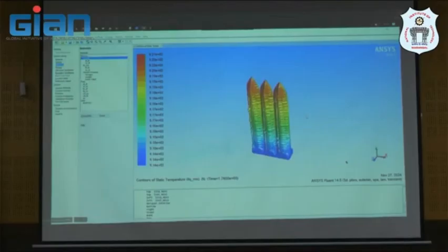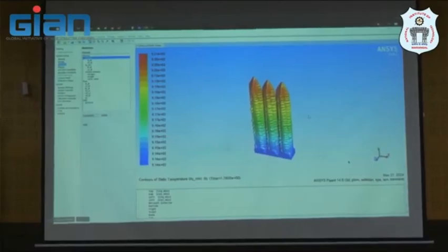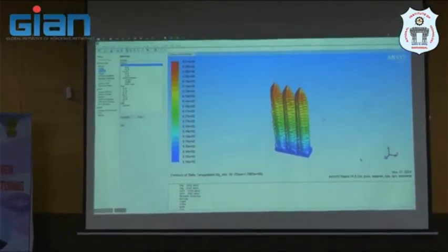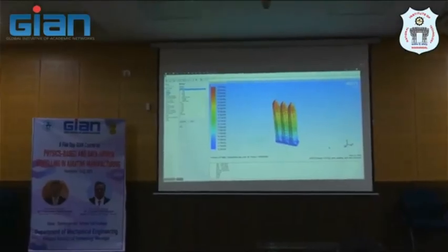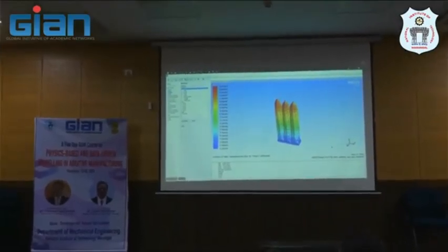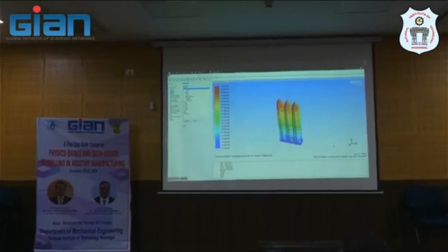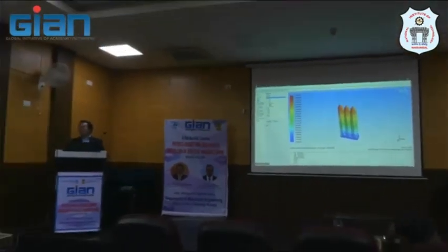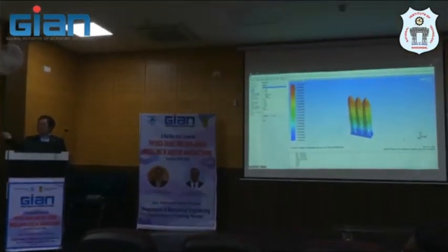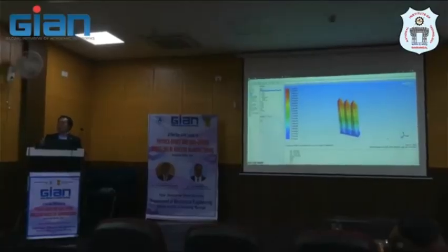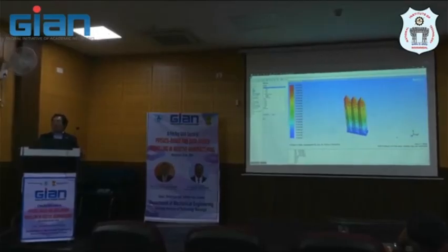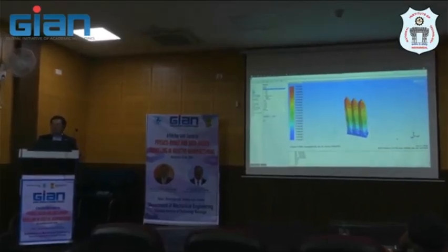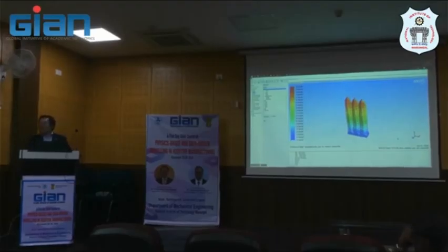So let's say you export the table, like the graph, it will probably be tabulated or a function, and then you call the temperature when needed at the centroid of the temperature field, so that you don't need to worry about it. It's just about the value of temperature and assigning the property for that. I think that is the usual standard approach we take. Let the computer work on it.